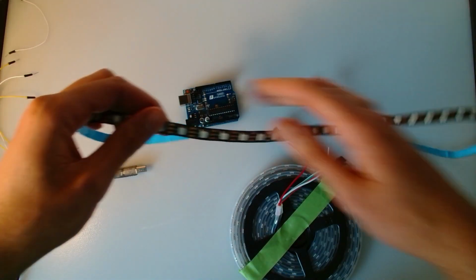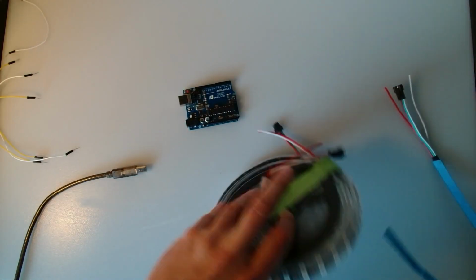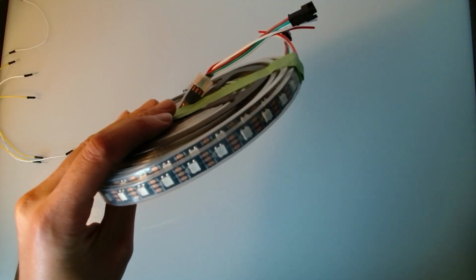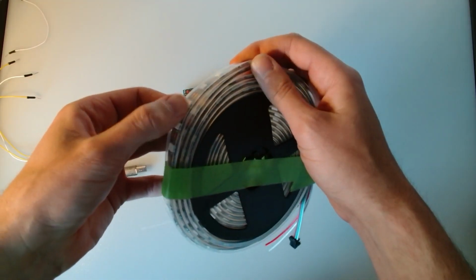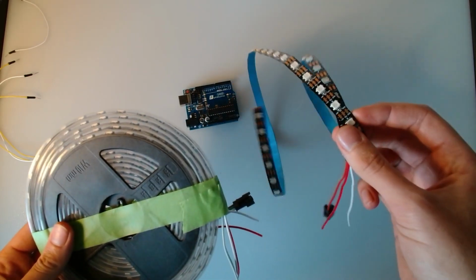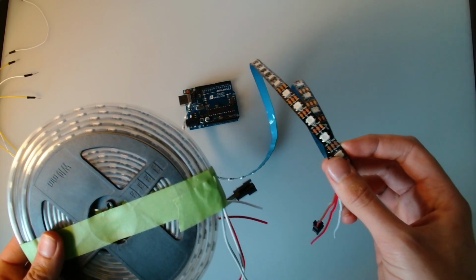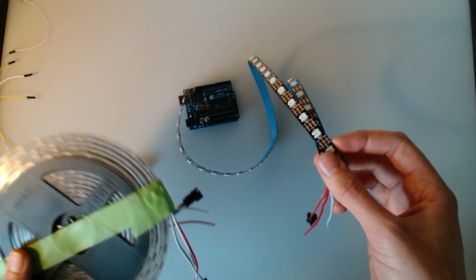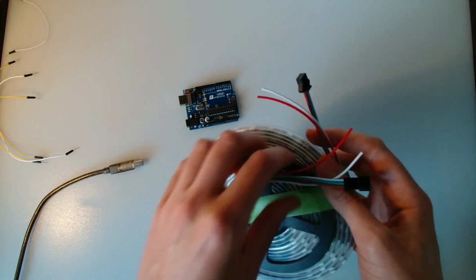These are IP30, 60 LEDs per meter, addressable LEDs, and these are the same 60 LEDs per meter, but these are IP67, which means they're water resistant, I think, rather than waterproof, which is why they're in this rubber casing. I ordered these first, and then I ended up going back and ordering these because for what I need to do with them, which is to put them behind the board of our backboard, our development board, these come with the adhesive strip on the back, and these ones don't. Anyway, I'm getting a bit sidetracked here.